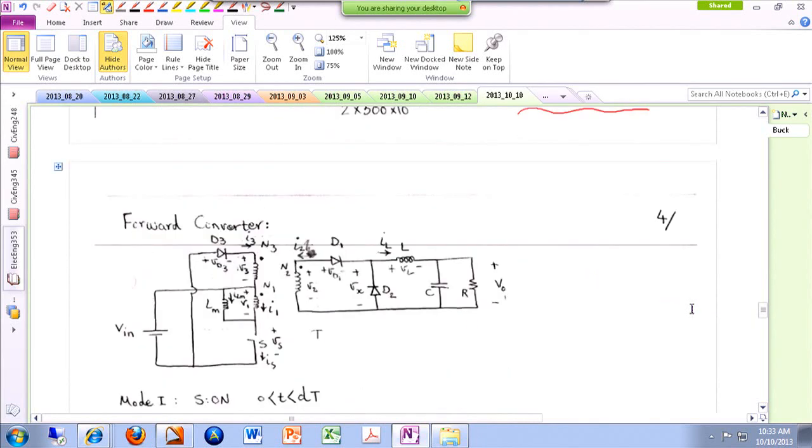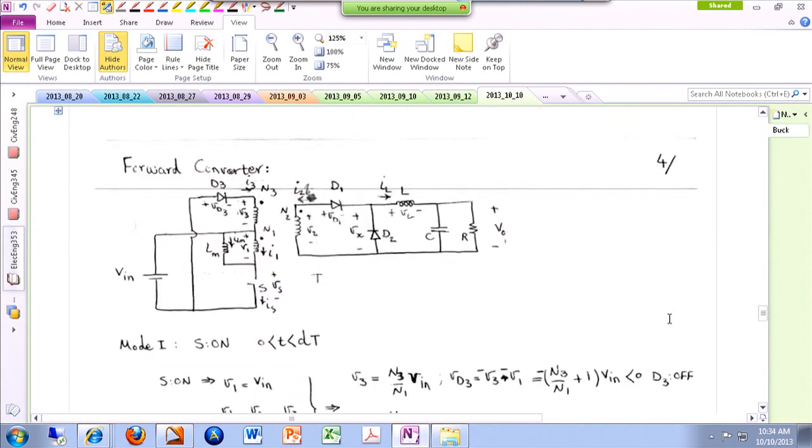All right. So this was all about the flyback topology, and the good news is we don't even analyze this under discontinuous conduction mode, although there are applications for the flyback topology, like in a power factor correction application, where you might use a flyback converter under discontinuous conduction mode, but here we don't do that. The equations are very similar to the buck-boost topology that we didn't analyze either. For some reason, buck-boost is always at a disadvantage because nobody is interested in analyzing it. All right, so let's move on to the next topology.